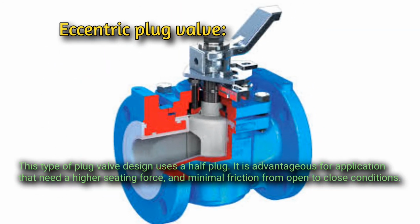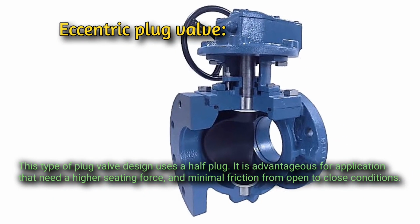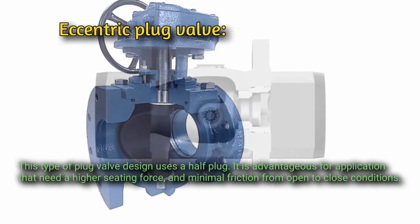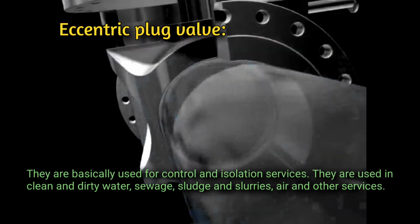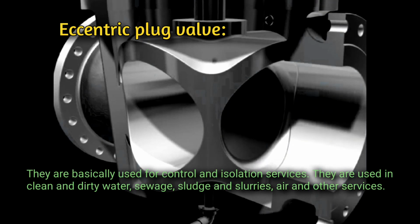Eccentric plug valve. This type of plug valve design uses a half plug. It is advantageous for application that need a higher seating force and minimal friction from open to closed conditions. They are basically used for flow control and isolation services. They are used in clean and dirty water, sewage, sludge and slurries, air and other services.